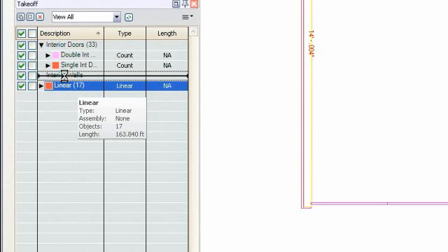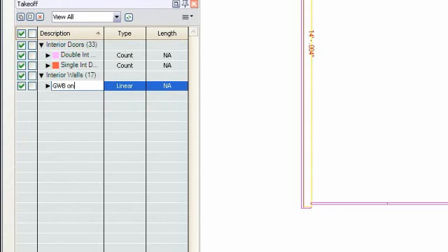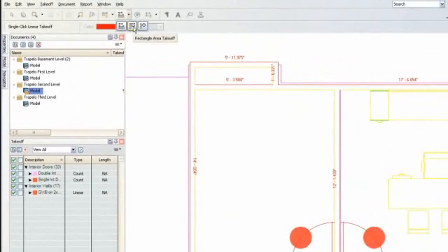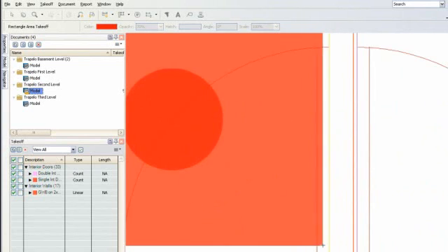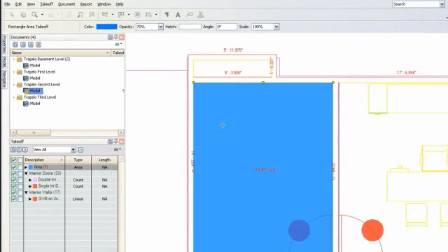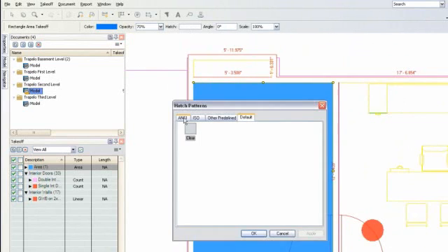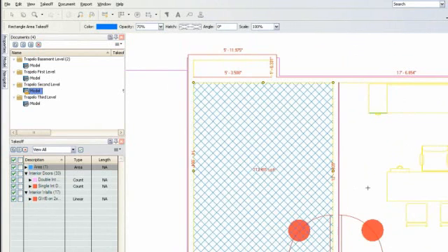For example, you may wish to calculate the number of studs and gypsum boards required for each section of wall, and the total number for the project, all of which can be easily calculated from the takeoff. When taking off areas such as flooring, Autodesk QTO provides tools to quickly mark out and calculate the area. This is particularly efficient when quantifying the area of non-uniform spaces, such as open-plan office areas and corridors. Again, colors can be used to identify different areas along with standard hatch patterns.